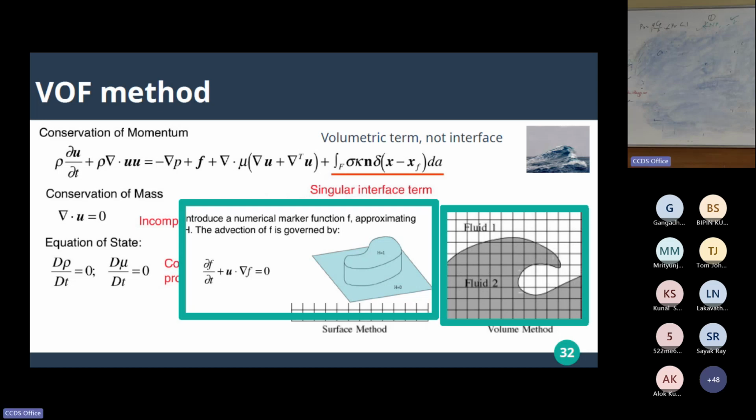From the top view, you will see some kind of interface, and there will be one liquid, there will be another liquid. So one has one particular transport property, the other has another particular transport property. Can I really get that by advecting an equation? And that's the way you really decide whether it is fluid 2 or fluid 1. In addition to your equations, you will bring one more equation for your volume fraction field.